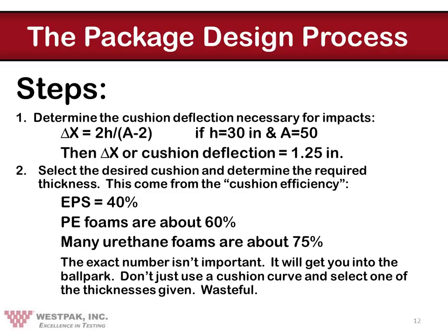So the first step in this whole process is to design the cushion system. And the first step in that is to determine the thickness of the cushion, or more correctly, the required deflection of the product in order to achieve the results that we're looking for. This is particularly important when designing the cushion system to protect against impacts during distribution, because they require the most deflection.